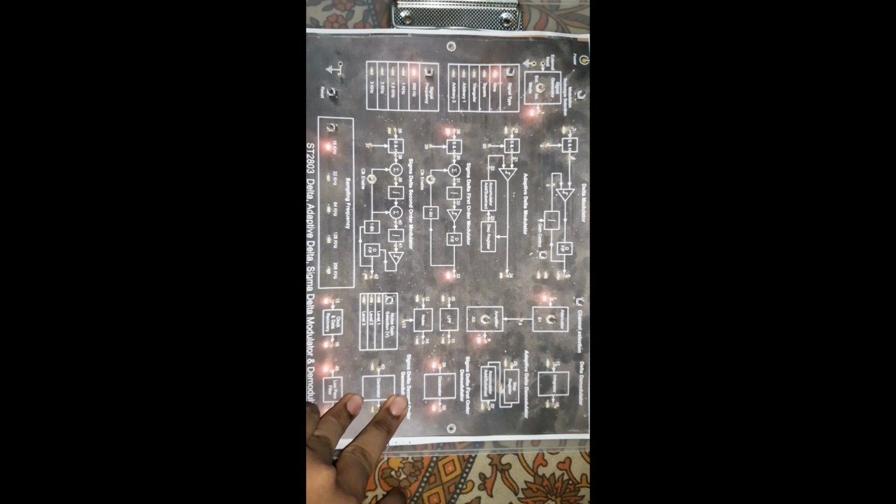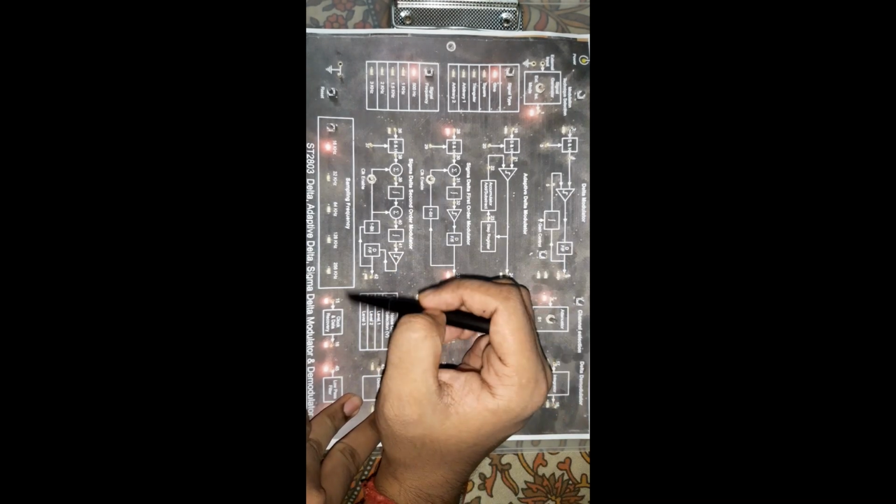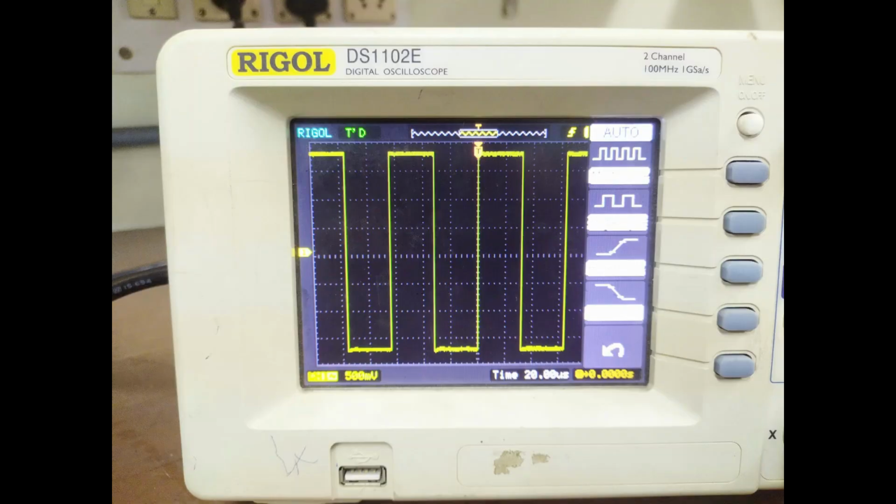Okay, and at the sample and hold circuit we are also feeding this signal. It is nothing but the clock signal, that is the sampling frequency of 16 kilohertz. If you calculate the time using the time division, you will find that it is near about 16 kilohertz. Actually it is not possible to produce exactly 16 kilohertz, because the crystal has some limitations also.